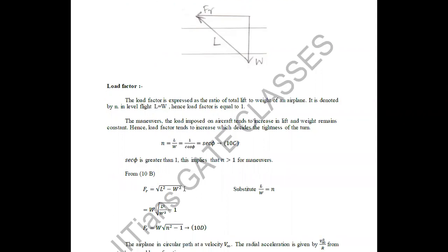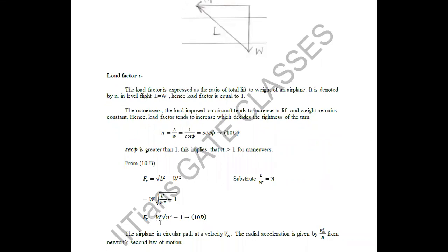If I take W outside of this square root, my equation becomes W into root of L square by W square minus 1. L by W is nothing but your load factor. When I substitute that, the resultant force becomes W into root of n square minus 1.